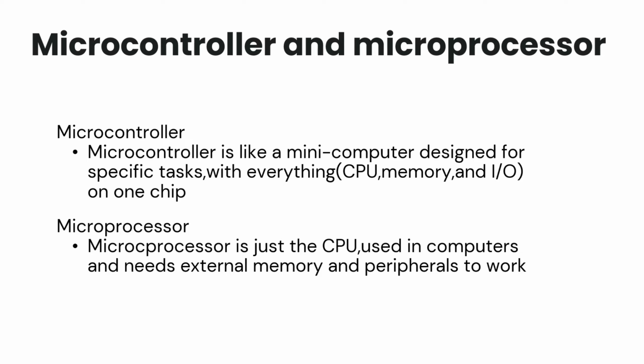Microcontrollers also include timers and counters, which are essential peripherals for time-based operations. Timers are used to generate delays, measure time intervals and schedule tasks, while counters are used to count external events. In real-time applications like a microwave oven, a timer plays a crucial role in controlling cooking time, generating buzzer alerts, and managing different operation modes.